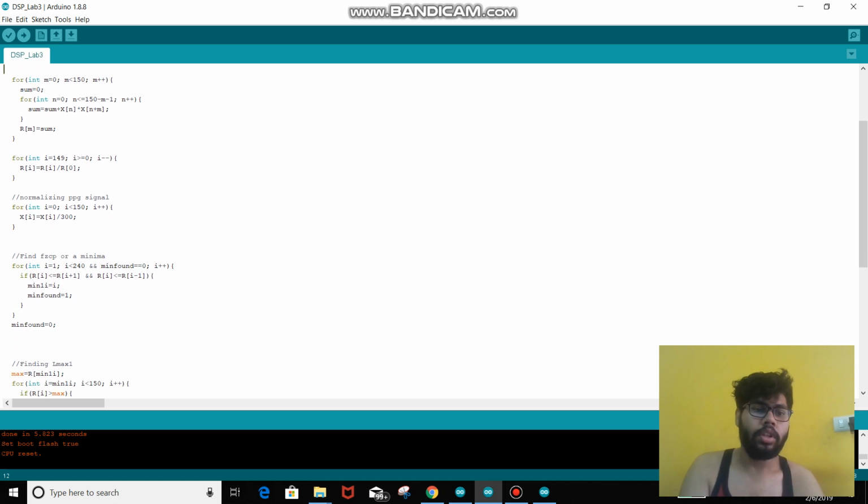Next, in order to find the frequency, we first find a zero crossing point or a minima. We will find a zero crossing point if the data has been pre-processed. However, if DC drift is present in the data, we won't find a zero crossing point. Therefore, we can make do by finding a minima.